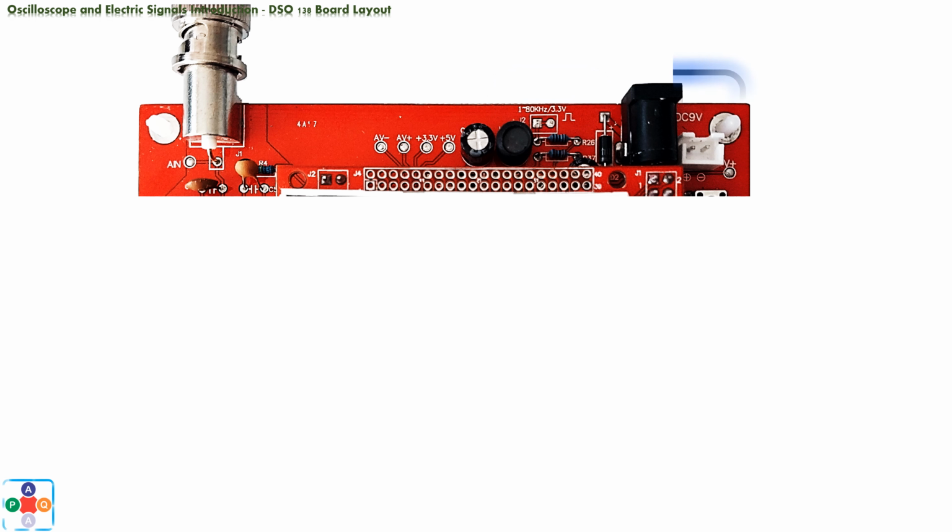Following, we have two power connectors: a black barrel connector for an external power source, such as an AC-DC adapter, and a white one used for direct connection to a power supply such as a battery. Do not use both connectors simultaneously to power the device. Use only one at a time.